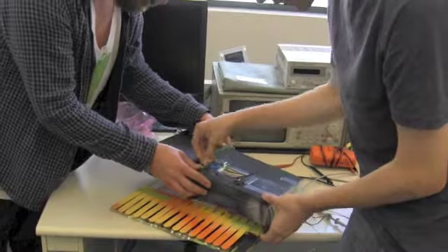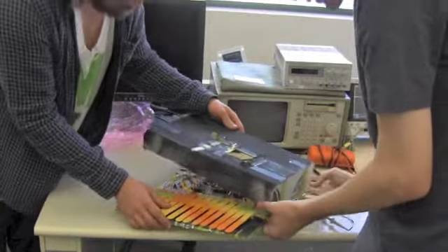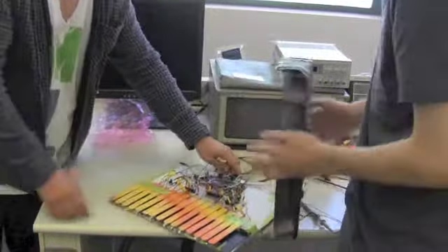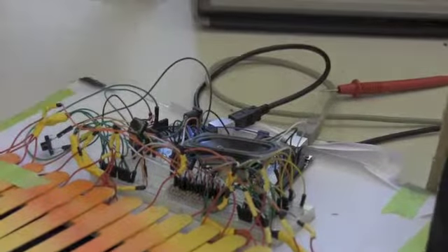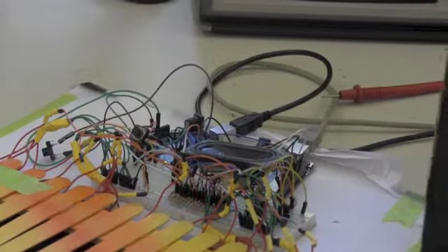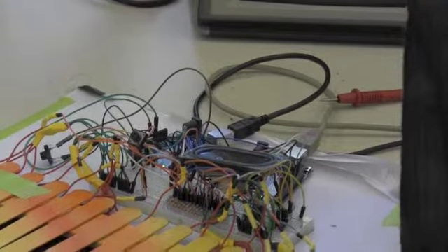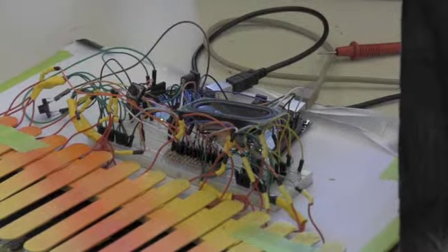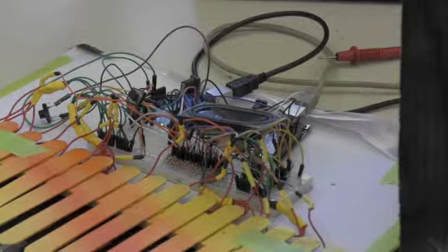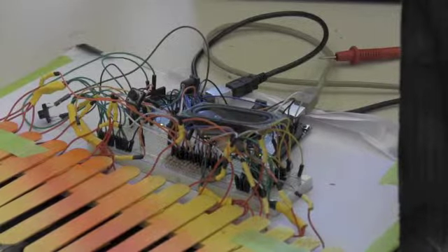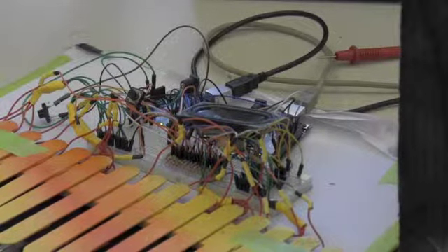There we go. So that's our two pieces of hardware. We have the two Arduinos there. They talk. One issue that we had to overcome was different clocks because the Arduinos weren't perfectly synced up. But we were able to do that by running it from the lower frequency to the higher frequency, so it was checking often enough so that it would get the correct notes. But yeah, only one of these is hooked up to the speaker.